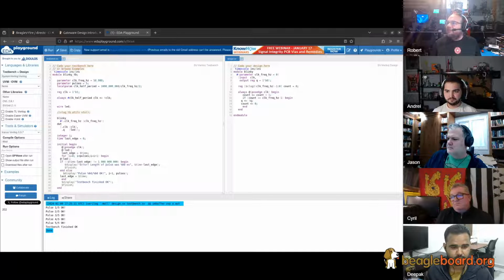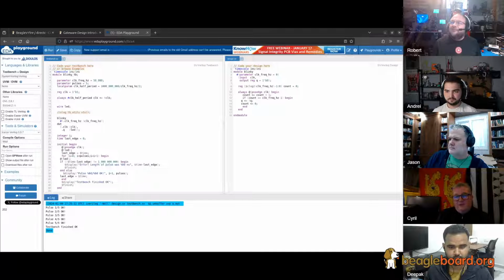Everybody has kind of their preference. I really like using Verilator. I found that for me that works very well. That does what I'm looking for. I'm basically writing my test bench in C++, and I can write something that will generate traffic or something that will observe the output of my circuit and write checkers in C++.